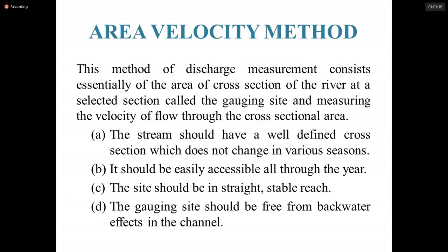So for this measurement, we need to select a stream or river that is flowing all through the year. The stream should have a well-defined cross-section which does not change in various seasons. The next is it should be easily accessible all through the year.